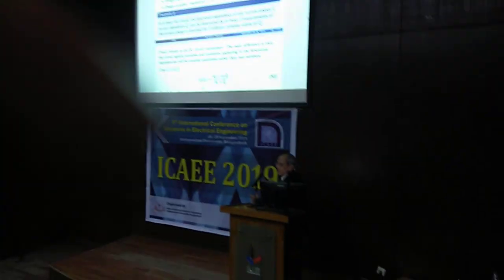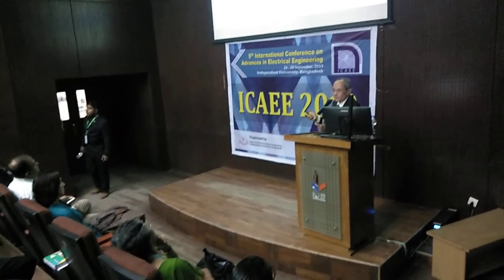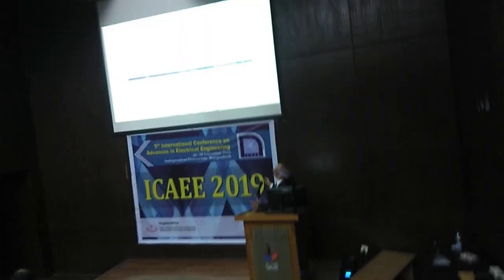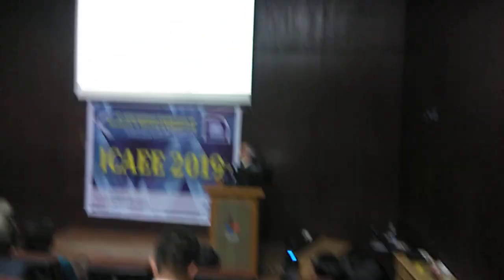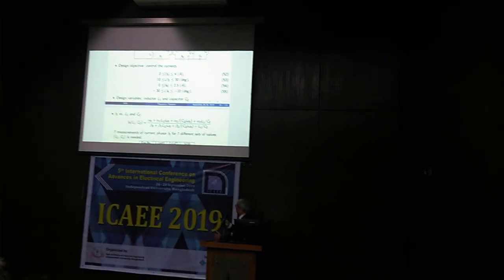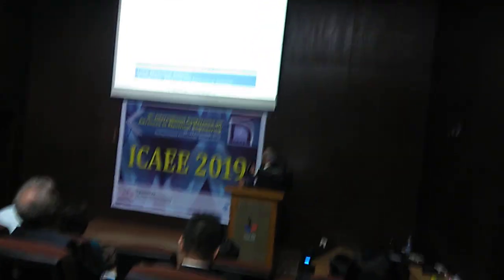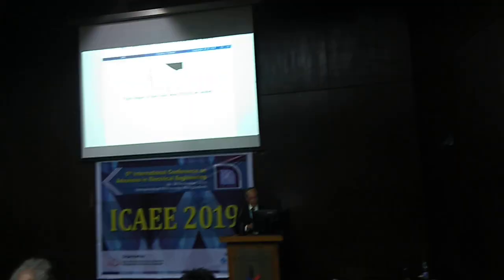You can do the same thing with an AC circuit, except now you have complex numbers. All right. So once again, in that circuit, here's a typical problem you can solve. You can put magnitude and angle constraints on the currents, and then you can solve for L1 and L2 that achieve that. Typical solution with a final result is the intersection of the values attaining each of the constraints.